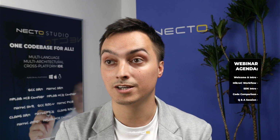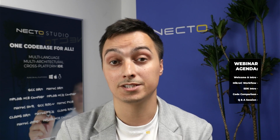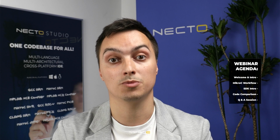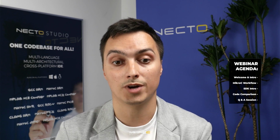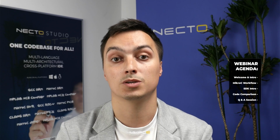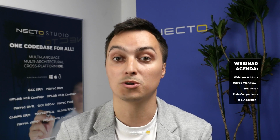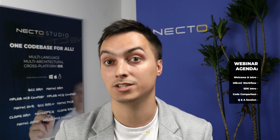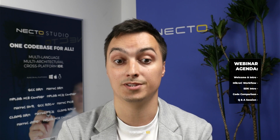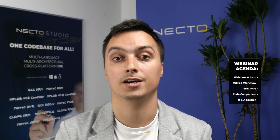You might think, okay, this is just an LED blinking. What's the big deal? But consider this. This exact code works on PIC, PIC32, dsPIC, AVR, and even RISC-V microcontrollers. And there is no need to rewrite TRIS or port register values. And you didn't even touch the datasheet. And you can swap boards or architectures and your code still compiles and runs. And that's the MikroSDK difference. And that's what NECTO Studio is all about. Writing embedded code that's clean, scalable, and architecture agnostic.